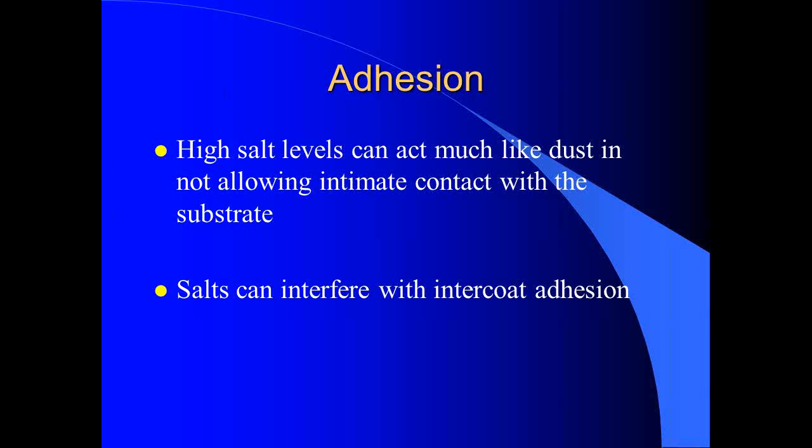So they did that. They pressure washed the lighthouse, got the salts off of it. They dried it up. They applied the primer coat, went home for the night, came back the next day and applied the intermediate coat, went home, came back the next day and put on the top coat. Several months later, the intermediate coat was pulling loose from the primer, and the top coat was coming loose from the intermediate coat.